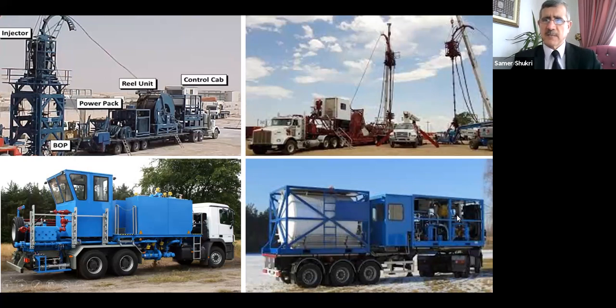After that, it can be pumped through the coiled tubing, here the inlet, and it can go down to the required depth to offload the well, or maybe sometimes we have drilling, we have a clean out. If the hydrostatic pressure is high against the formation, what will happen? There will be a loss into the reservoir, and there will be no circulation to the surface to clean this sand or scale. In this case, the clean out operation will not be successful.